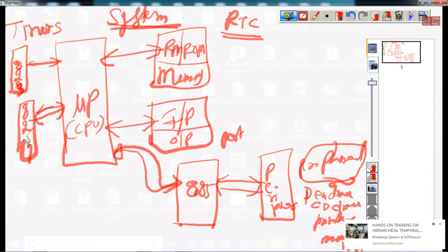One device can be TTL, another HMOS, other devices CMOS, and other ICs. All these devices we are connecting to make a system, so the logic levels of one device and another may be different. Connecting in a compatible manner is called interfacing. So in microprocessors, interfacing is the word we use, not connection. This we already discussed.